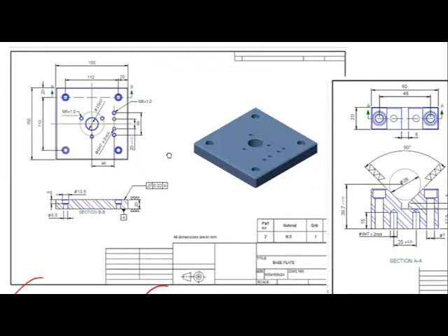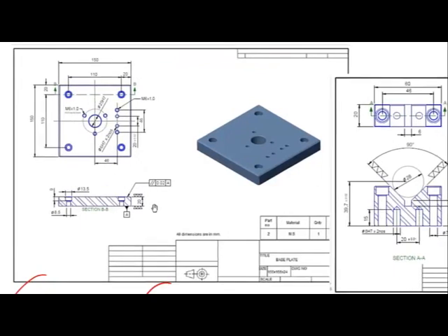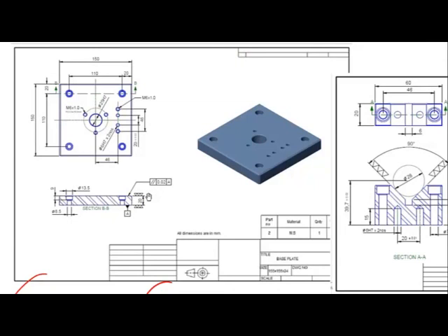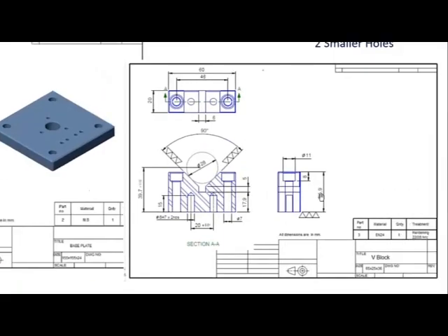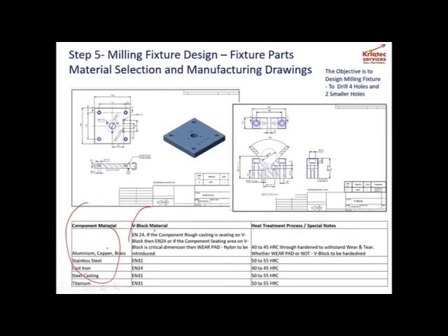If you could look at it, both have to be ground, because when you are trying to assemble the components, the grinding symbol is given. Almost there is no mistake here. But if you look here at the V block, this 35.9 could have been changed to 37, because it's not important. I'm just changing it to 36. Rest of the time there is no error. What is very important is that you should know that if my component material is stainless steel, the V block materials are different. And similarly, if my component has a critical dimension, then in the V block I need to introduce wear pads. All these play a key role in the fixture design.